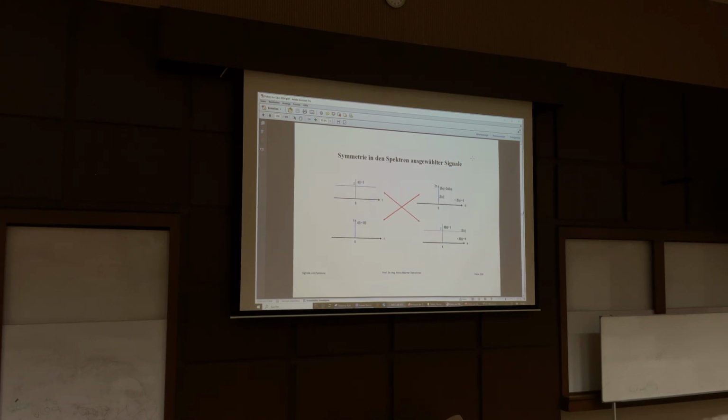Here, same. A constant value gives me a constant value in frequency spectrum. This constant value has for all times the same amplitude. So if you would integrate this signal, that would have an infinite energy, and all the frequencies are present, theoretically. And if you put here a pulse, gives me a pulse in the spectrum.